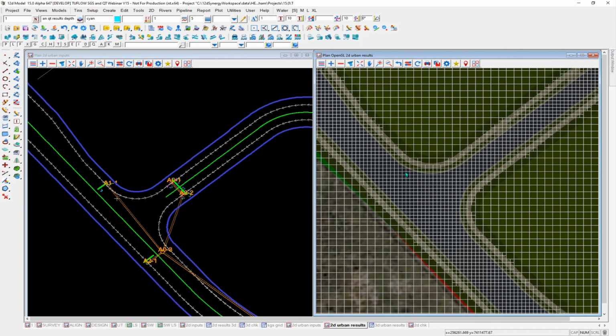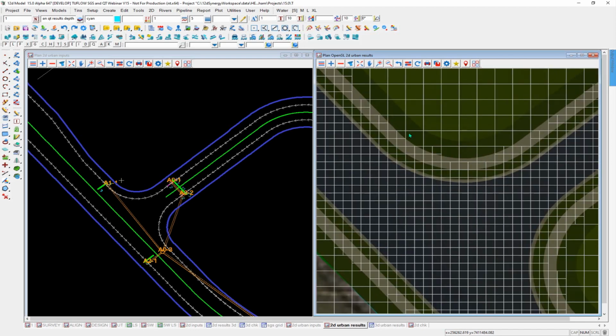When I'm inside the polygon, I get a refined grid. So out here I have my standard 1 meter grid that I asked for, but then because I had a nested level of 2, it's gone down and made it half. Now I could have made a nested level of 3, which would have made it down into eighths, but always transitioning 2 at a time.